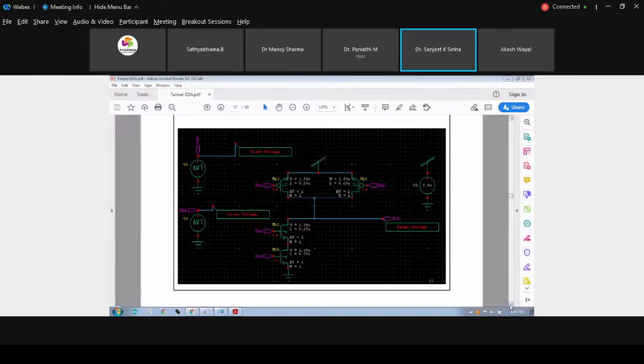According to that design, for example if we are using A and B, then this is A, this is B, this is A, and this is B. The first upper PMOS has A and B, and at the NMOS side also A and B. This VDD is coming in the same way as we considered for the inverter. Once you simulate this NAND gate, we will have the actual output. Go for next.